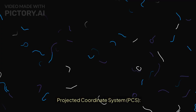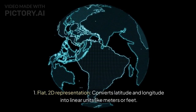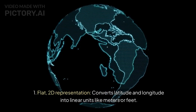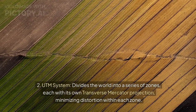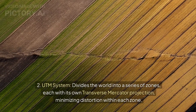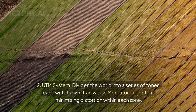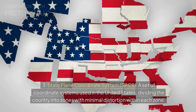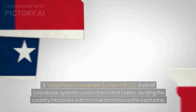Projected Coordinate System, PCS. 1. Flat, 2D representation. Converts latitude and longitude into linear units like meters or feet. 2. UTM system. Divides the world into a series of zones, each with its own transverse Mercator projection, minimizing distortion within each zone. 3. State Plane Coordinate System, SPCS. A set of coordinate systems used in the United States, dividing the country into zones with minimal distortion within each zone.